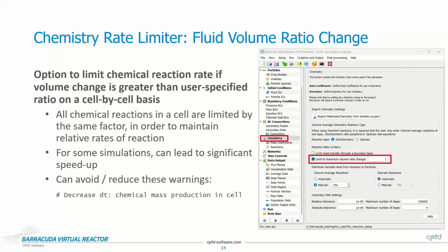But the benefits of the faster solution time should always be weighed against the possibility for a loss in accuracy in those few cells that might have the really fast chemistry. And the decision of whether or not to use this option should be made on a case-by-case basis to make sure it's appropriate for your simulation.